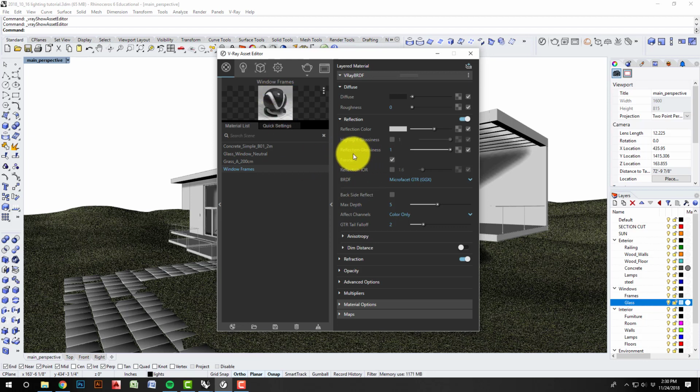The other thing we can do is control the glossiness itself. And what that does is sort of blur the edges. So keep an eye on this. Maybe it's easier to see it on the full reflection. Keep an eye on this little white spot, this shiny spot, and some of these reflection lines you're seeing in the sample. If I knock this down to like 0.5, we'll say, and let that render, you can see it sort of blurred all those fine lines.